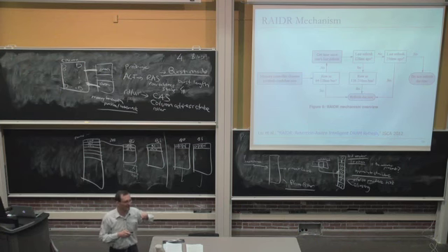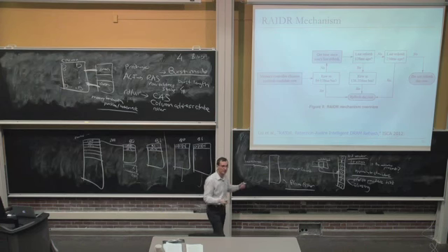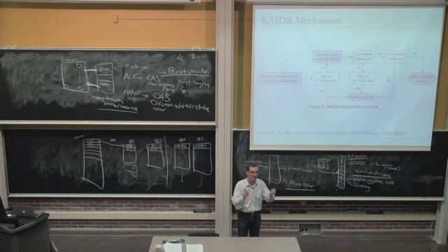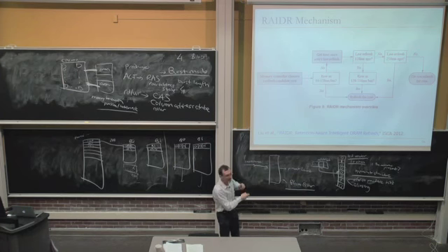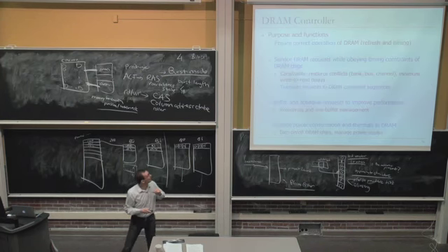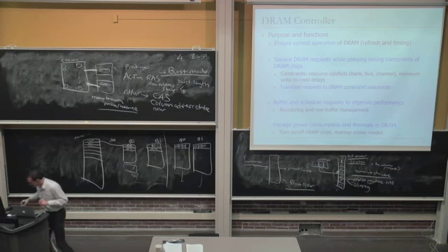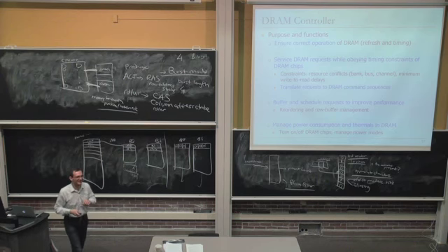Maybe you should read the paper. We'll post the paper if you're interested in this. Because there are other issues, like refresh time actually turns out to be dependent on temperature. As temperature increases, you need to refresh more frequently. So you need to adapt the system, and the paper describes how you adapt the system to refresh more frequently. Okay, so let's move on from the refresh. Looks like you guys are interested in it.